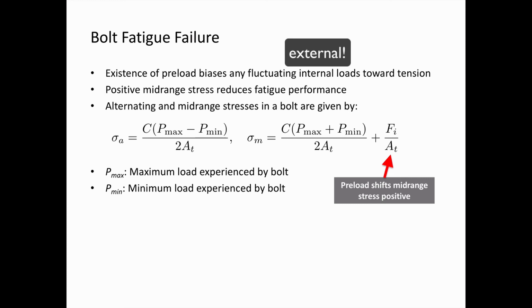You're going to have to take into account the stiffness coefficient as well as the preload in these calculations. Once we have these stress values, we can apply standard fatigue failure criterion, and we can also calculate a safety factor with respect to fatigue.